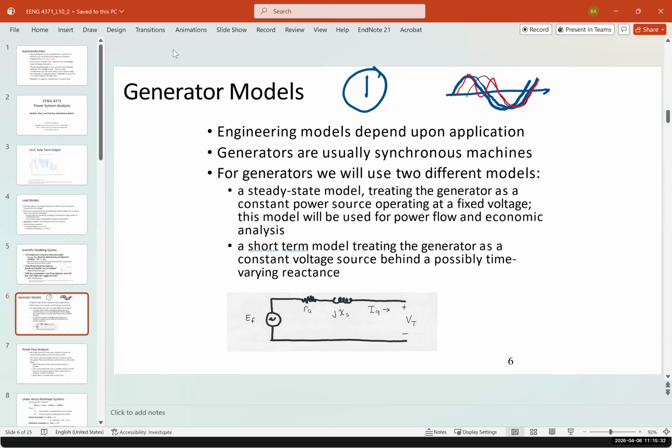First of all, the mechanical part: to heat up the boiler, it takes maybe 5-6 hours to reach a specific temperature if you're using a coal power plant or even a gas power plant. And then you have to match the voltage and the frequency and the angle. So it's not a simple flip of a switch. Sometimes it takes 12 hours. For a nuclear power plant, it takes much more, sometimes 24 hours, even more than that. So that's the reason matching that and putting schedule, maintenance is a very difficult task.